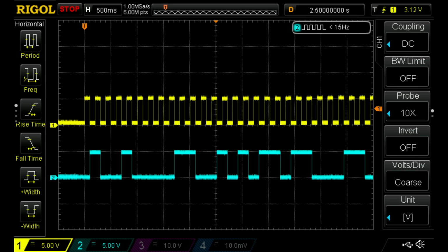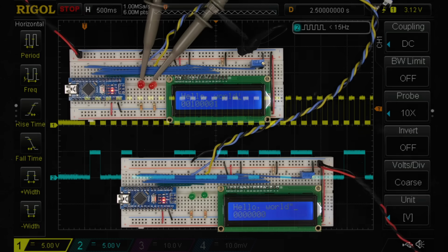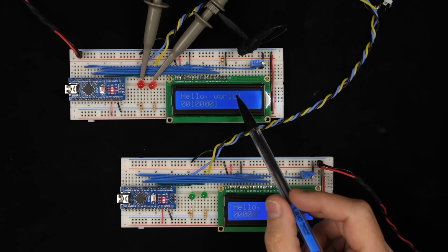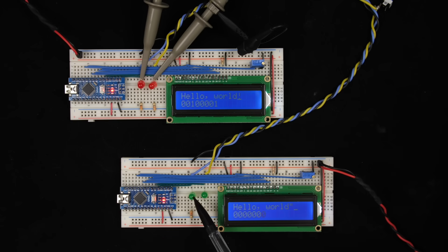As long as the data bits always line up with the clock, it's okay if the clock drifts a little bit. This is a really important aspect of engineering, to design systems that can deal with things going wrong or deal with imperfections like this. In this case, it's timing, and because our clock doesn't have to be perfect, we can get away with cheaper, less accurate timing hardware. But of course, at this point, we're still not using the clock for receiving, so we still may get some of these errors if we're not perfectly synced up. So let's take a look at what we can do about that.